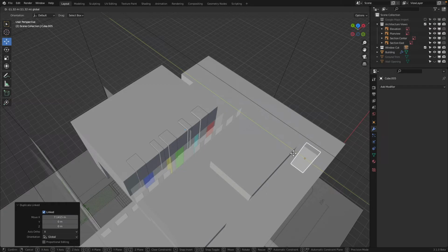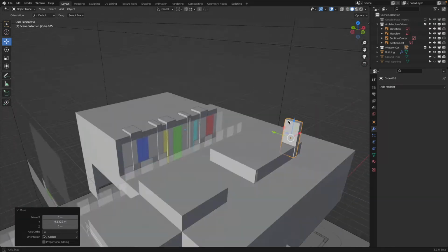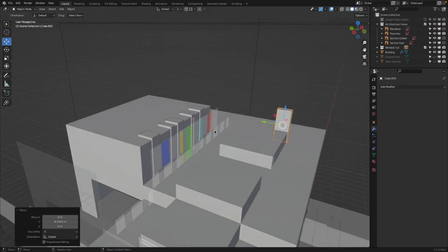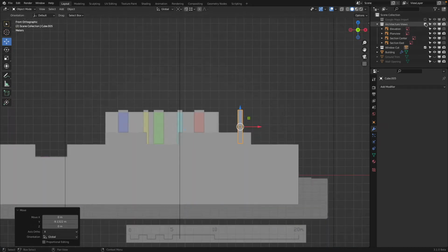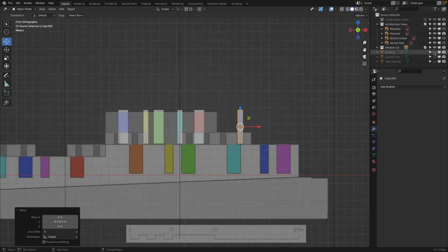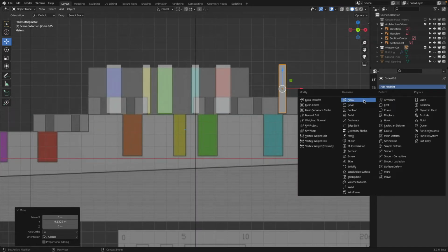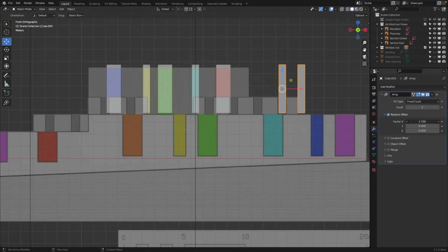Move, hold Control, and actually no, it doesn't snap because it's kind of like doing a Boolean cut, but it's okay. You see how far I moved this over, just so you have the same overlap. That is fine. Because now, array modifier. Why make myself a lot of work when I'm holding Shift and then drag this?